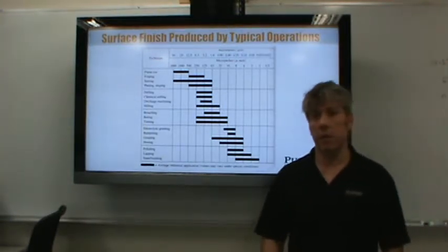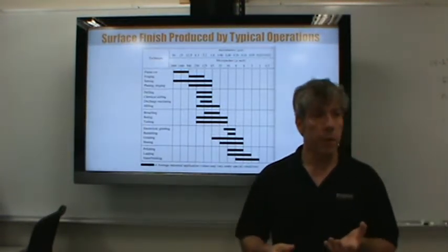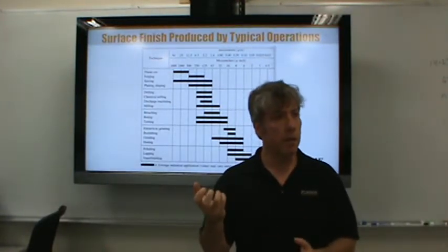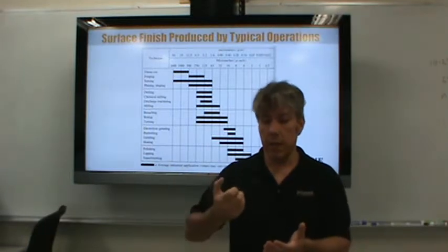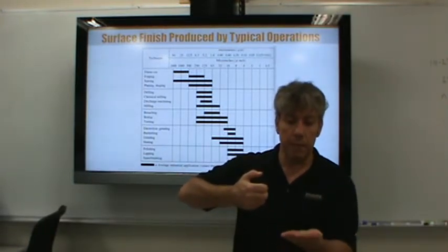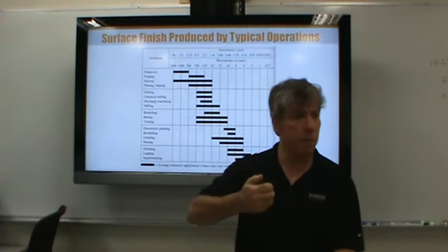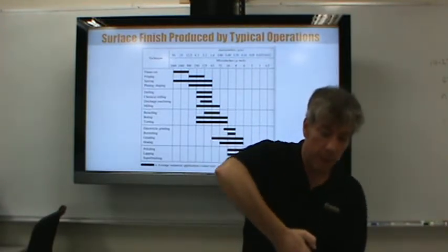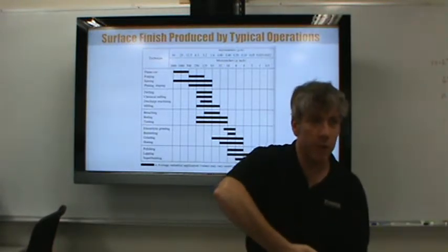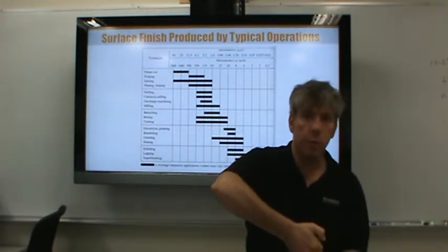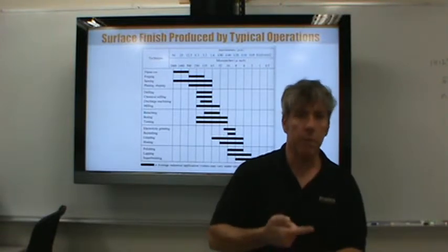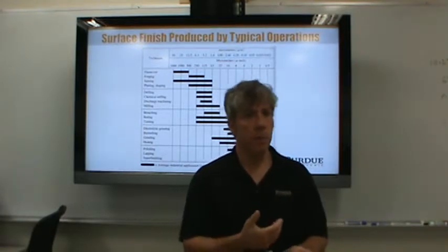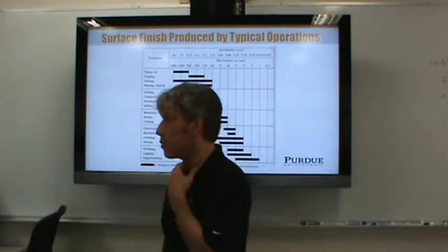Electro discharge machining is really interesting because basically you have the opposite part of what you want to make, typically, and you put the blank material down into a vat of, I think, oil or something, and you apply high voltage across, let's say, the male part, and you drive it. You don't actually drive it into the female part, you get it close to the material, and what happens is sparks jump across and actually blow away material on the workpiece. So you can make the shape that you want. It's really an interesting process.